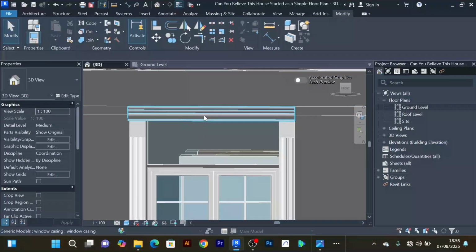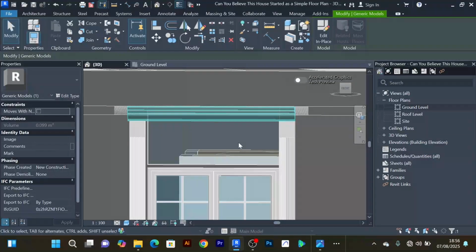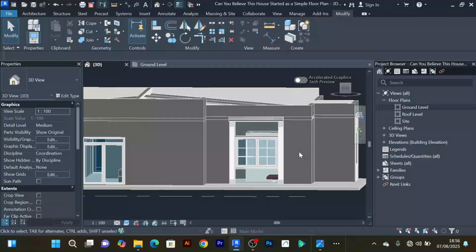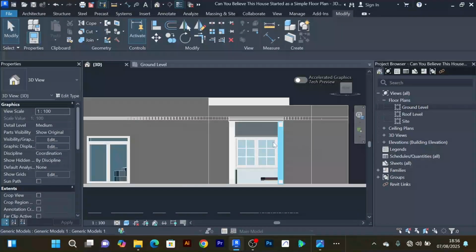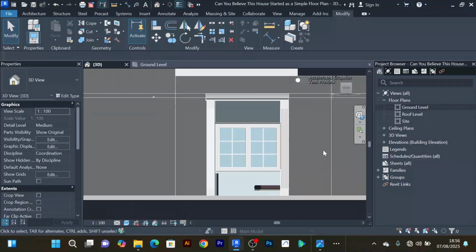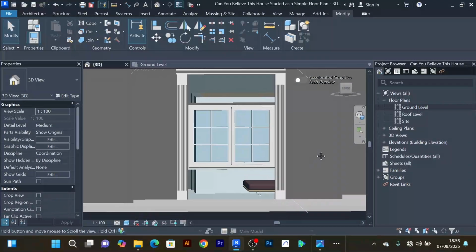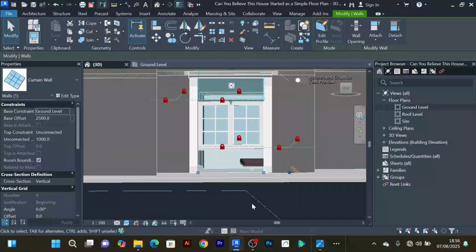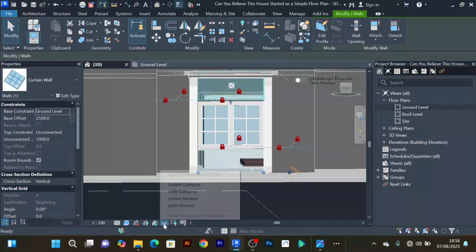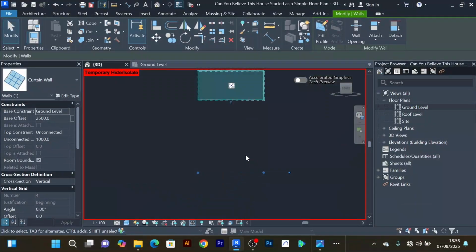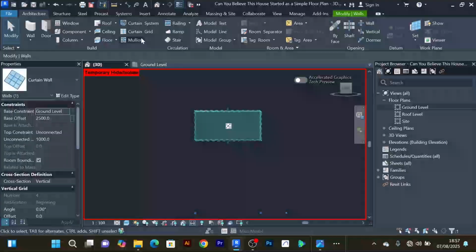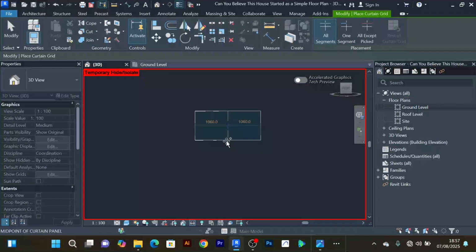So that's what we have around the window and the curtain wall. This curtain wall, I'm going to change something on them a little bit so that they give the vibe of a window as well. I'll click on it. I'll come to this isolate. I'll isolate it. Then I'll come to architecture. I go to grid. Then I can split it equally here.